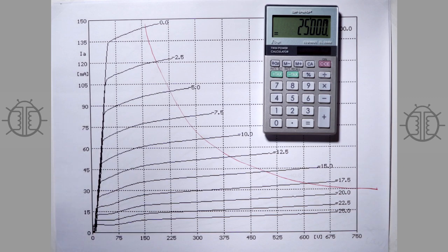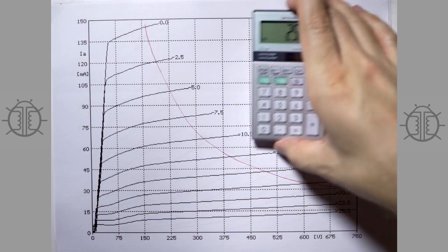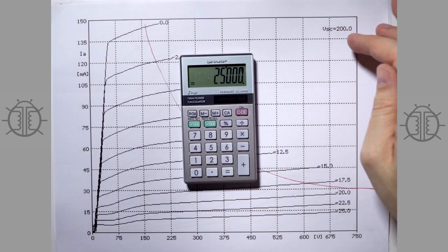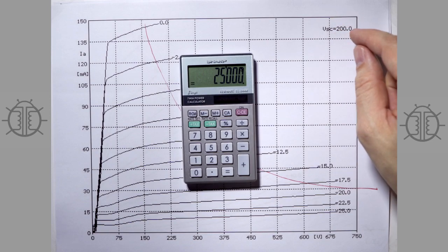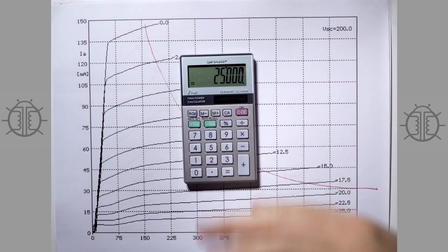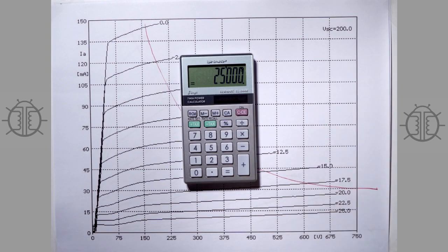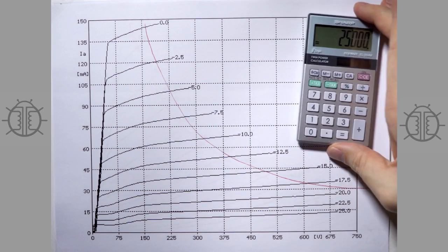And so that's pentodes for you. The way that they accomplish this is basically the cathode and grid system only see the screen voltage. And so the plate can swing around without affecting the electron beam that's going through to arrive at the plate. So that's how that works.